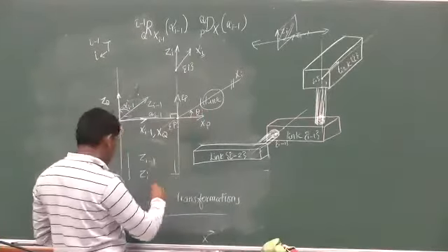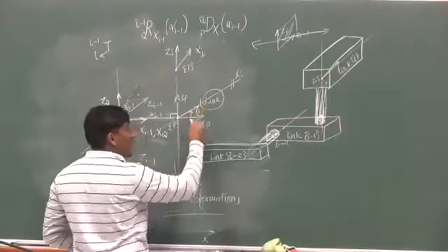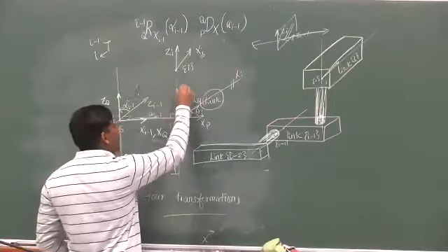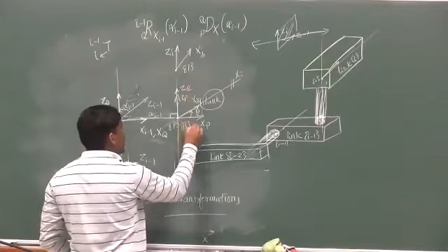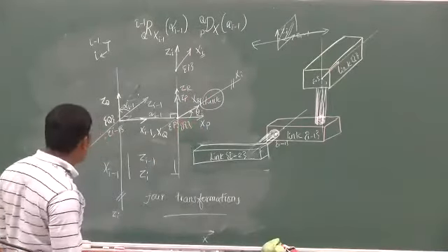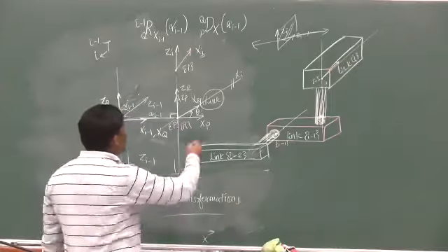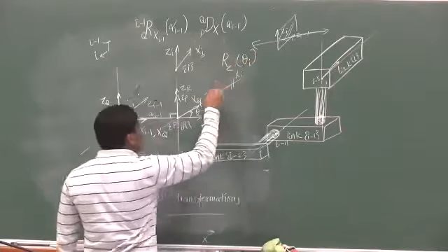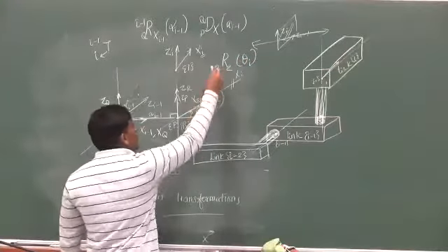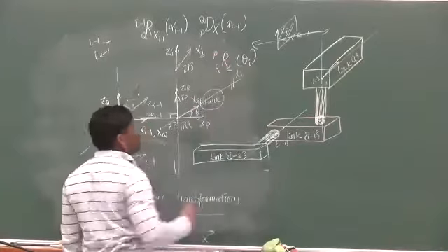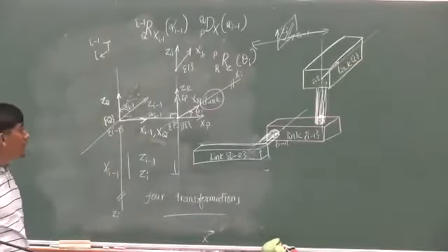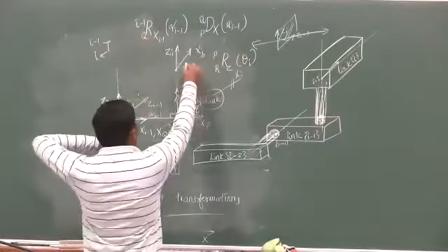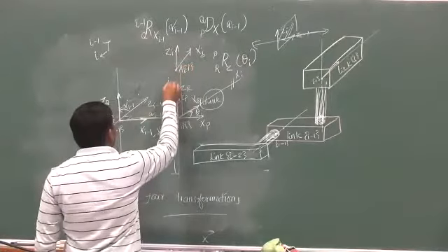Now we got a new x-axis, which I am calling xr, and because of that I get another frame, zr. So now you can see the r frame has come. Is the r frame a distance apart? No, it is only oriented apart. It is rotated about z by the angle theta I. The r frame information I can see from P like this, right? Now what is remaining? R and I are only a distance apart, and that too along Z. So I can travel this distance, which I call di.